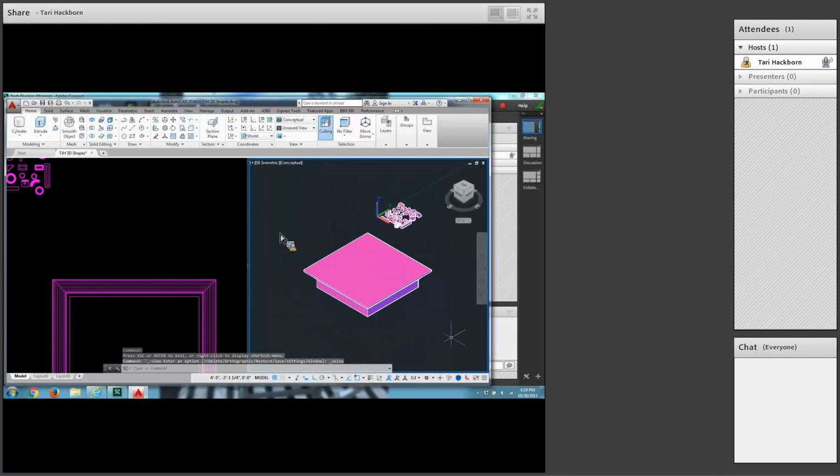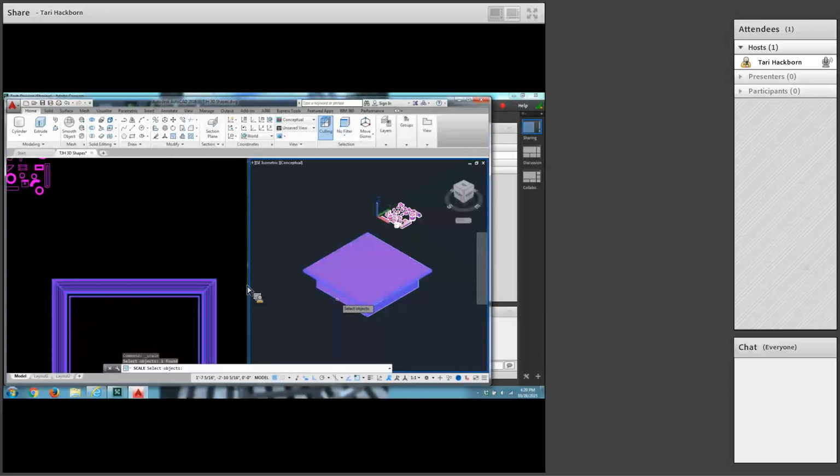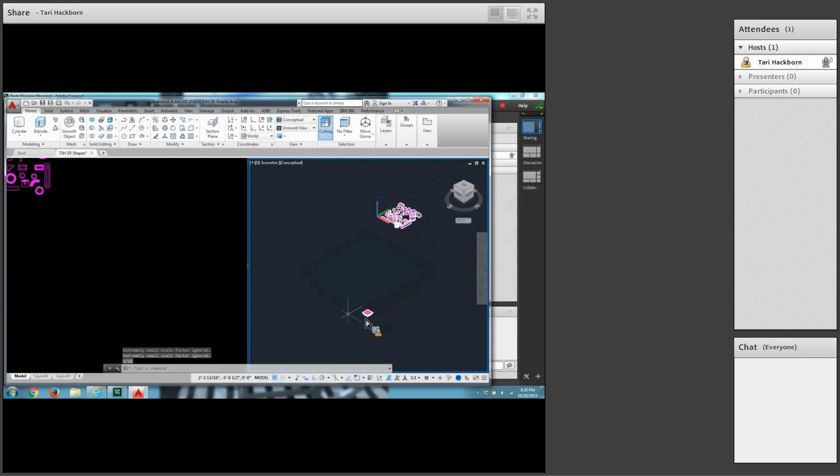That means step 71, it says you're going to scale it 1/12 of its size. We'll just scale it back up by 12 when we bring it into the patio. Okay, so scale, where do you scale? Right here in the modify panel. Okay, pick the object, press enter, pick the bottom corner as a base point, and type 1/12, enter. It's little now. Okay, now you have a little one.